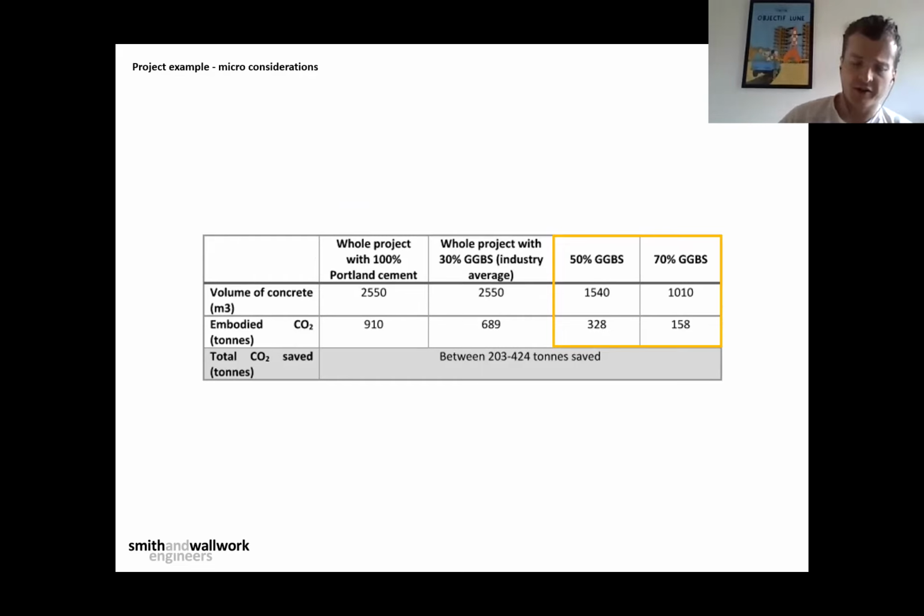And so we basically took your normal piled solution, with a bit of work and analysis you reduce that down to a simple raft, you quantify the movements, and then make that raft as low carbon as you can. And overall, slightly hard to get an exact answer on the ECO2 because of the variations in where it comes from, but we think somewhere between 200 and 400 tons saved. So yeah, that's my fast whistle-stop tour of the basement design.